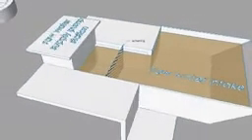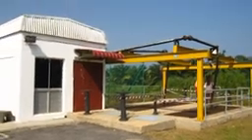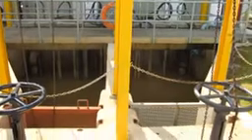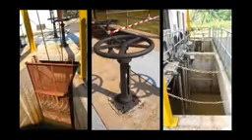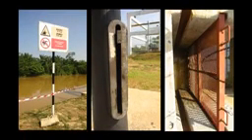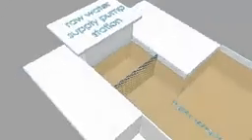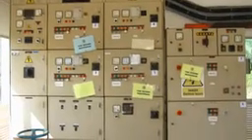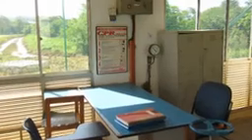Raw water intakes withdraw water from a river, lake, or reservoir over a predetermined range of pool levels. Floating debris such as wood, leaves, aquatic plants and others are screened at the intake. After screening, the denser suspended matter is removed by allowing the water to pass through a chamber where it settles down to the bottom. Submersible pumps abstract and transfer raw water from the intake to the water treatment plant.